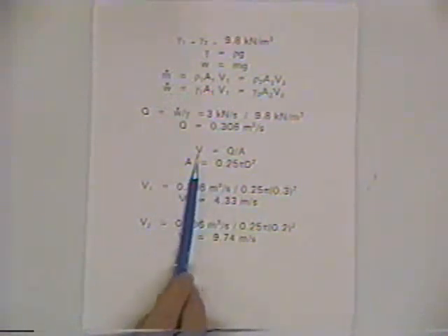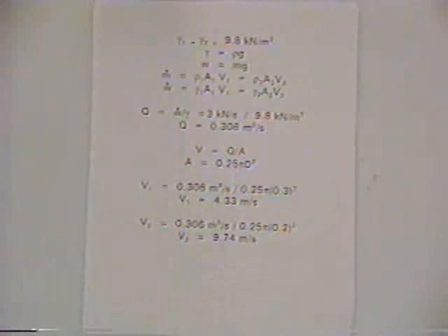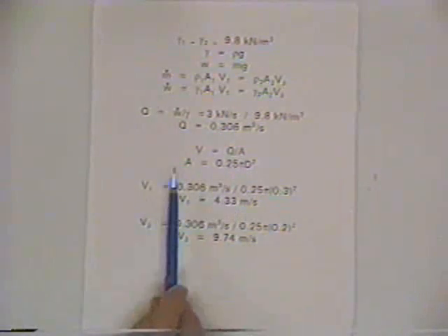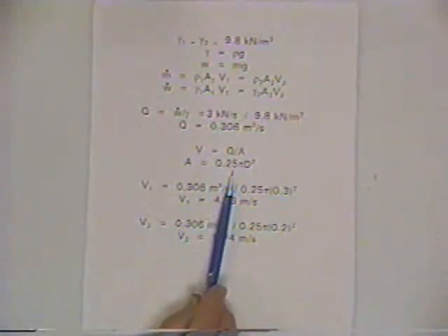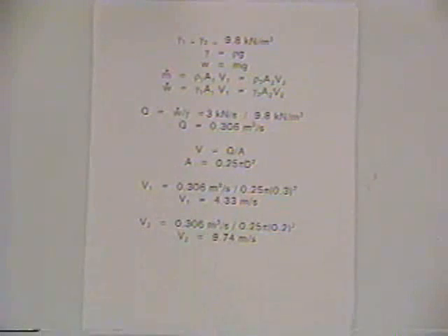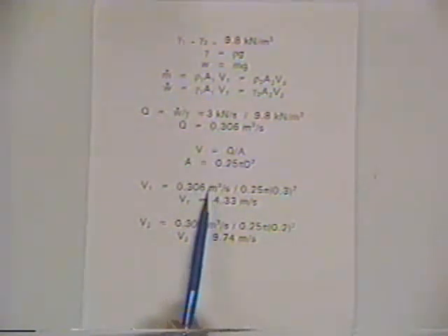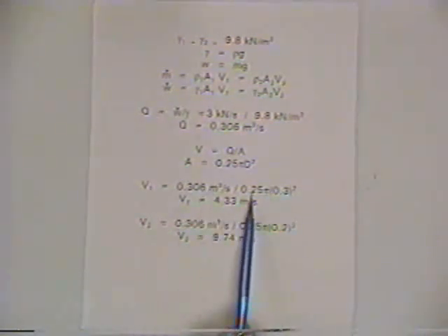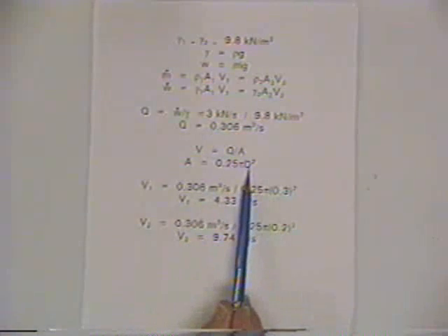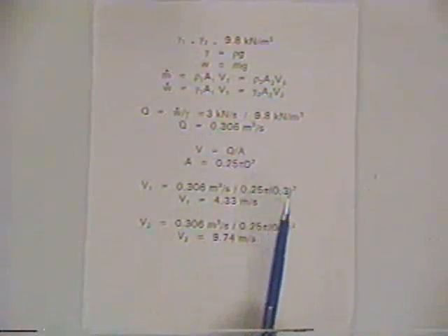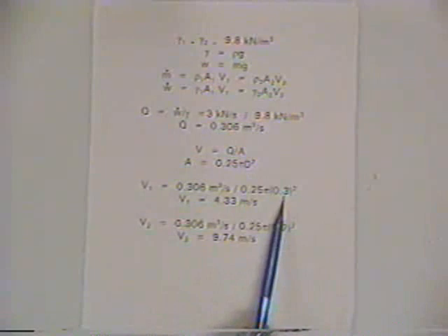Velocity, the mean velocity of flow through this area A is just the Q divided by the A. And the area of a circle for a pipe is 1/4 pi times the diameter squared to get the A term here. And so we take the volumetric flow rate, the discharge rate, and divide it by the area, which we'll compute simply by substituting in a diameter of the pipe.